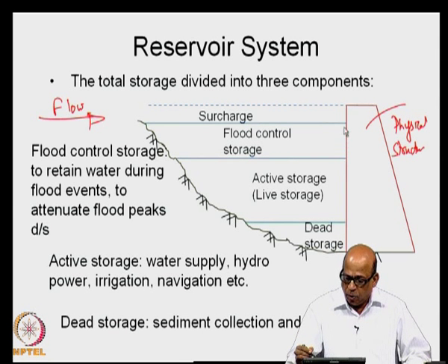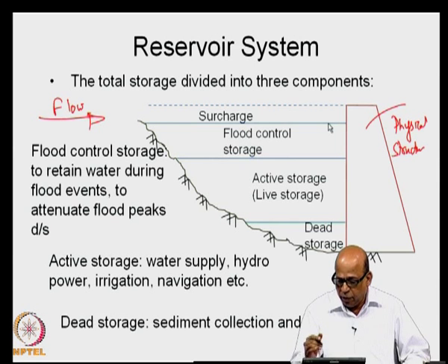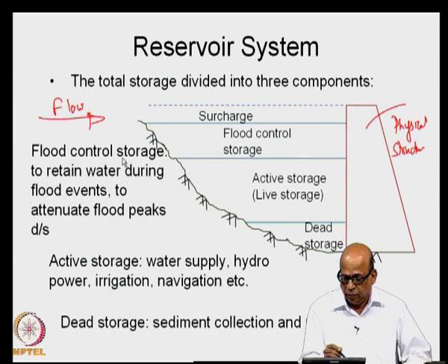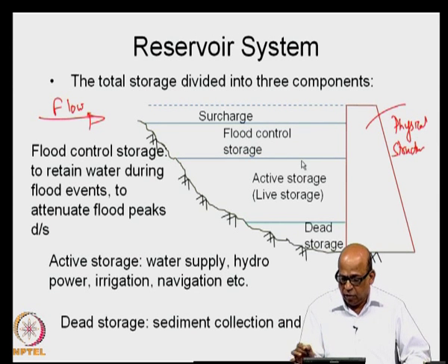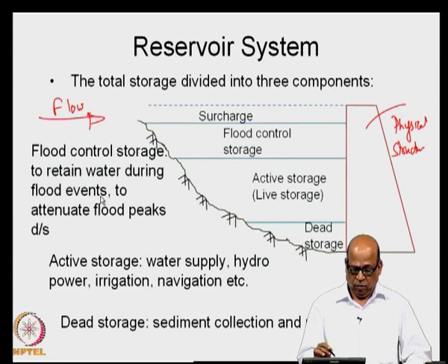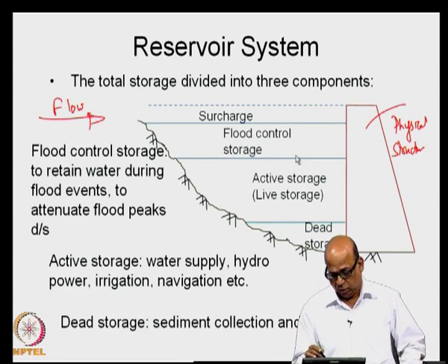Then you have flood control storage. Now, the flood control storage is the storage that you provide as a buffer to absorb the flood waters. In many cases you can combine the active storage with the flood control storage by making use of this amount also during the non-flood seasons. We will come to all those details later in applications. However, the flood control storage is that particular storage that you provide to absorb the floods, to attenuate flood peaks downstream. So, this is what we do.